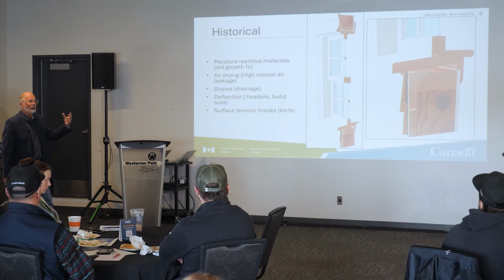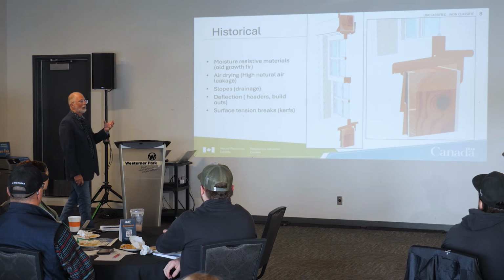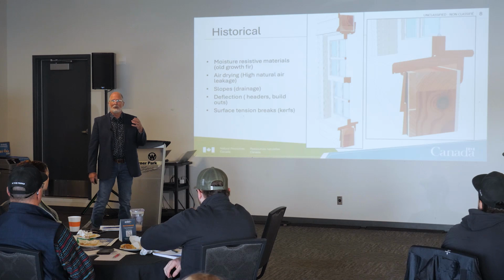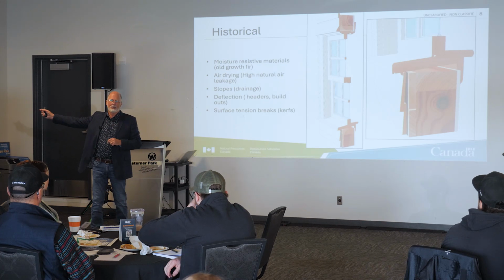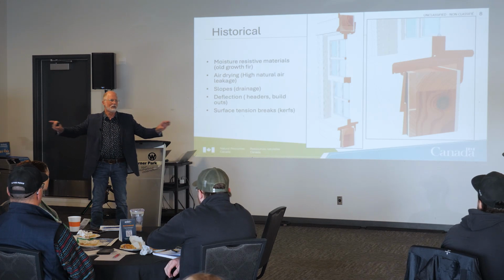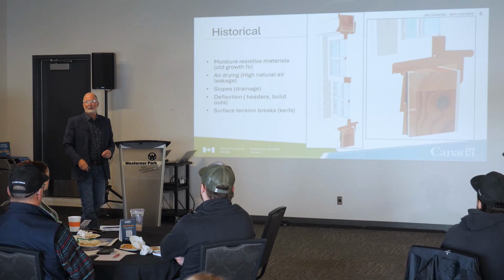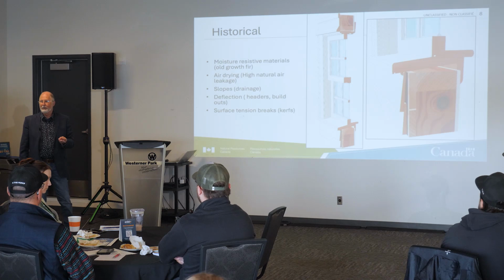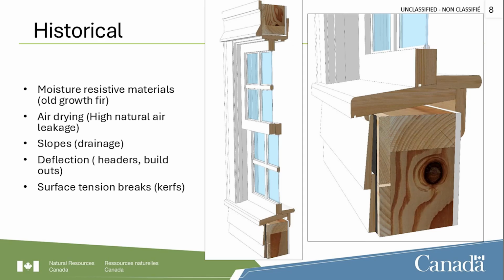When I started framing in 1978, we always had old growth fir, right? You would only see a knot every 10 boards, just straight grain in the wood. And very resistant to moisture. So fir lumber, super resistant to deterioration from moisture. Now we're using 10 to 12-year-old trees to produce 2x4s and 2x6s. So very different in terms of what the material can handle.